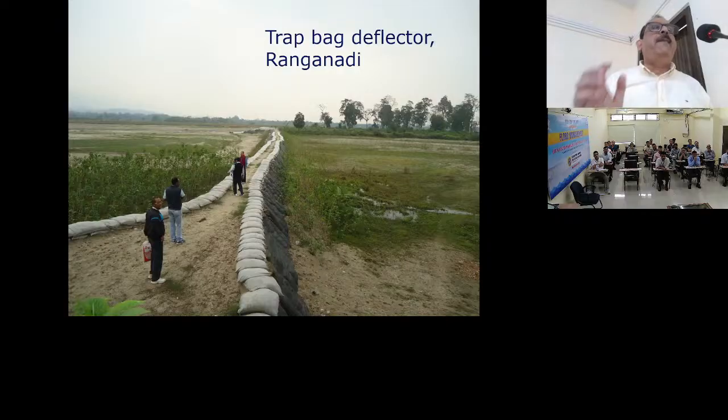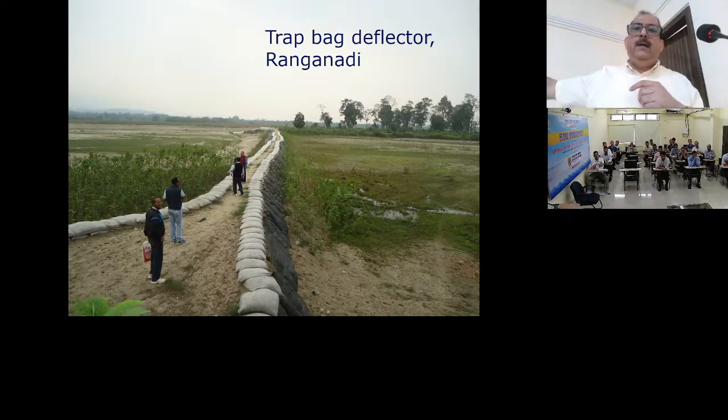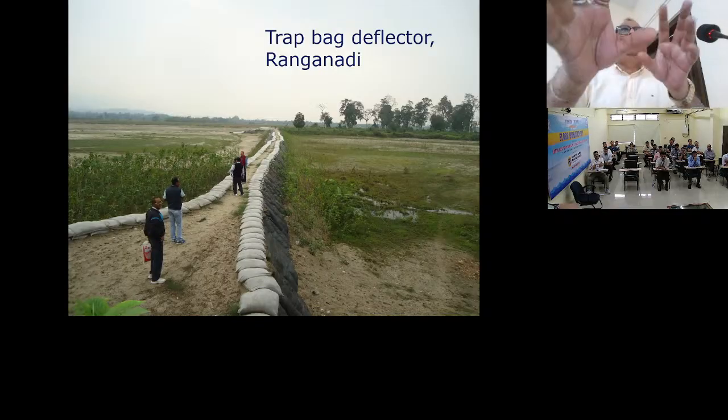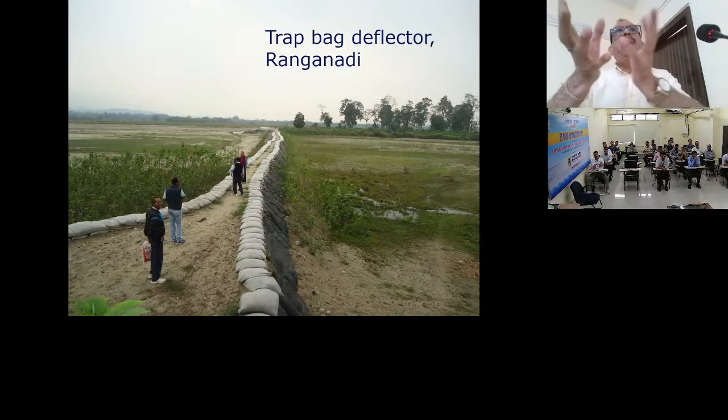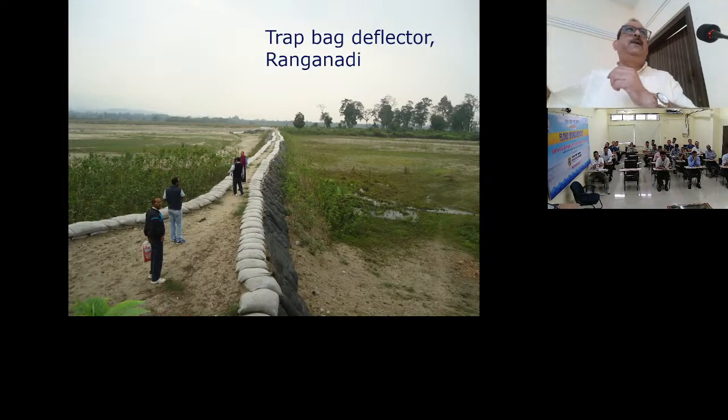Say you want an embankment very fast. Time is not there. Simply purchase the bag and then fill it up with sand. You require some machine for that. See, you have to put the sand along with water. Water will go out from the bag because it is porous. It will keep the soil there. And then within say 1 or 2 days, you can construct an embankment like this. Very useful.